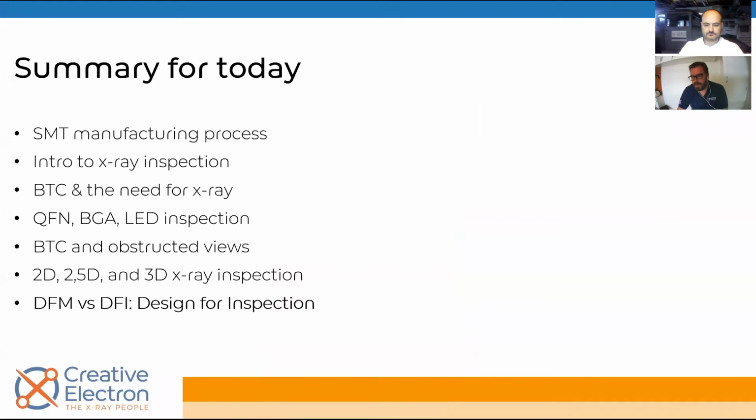So here's a quick summary we're going to go over today. If you've joined another one of these webinars, you're probably familiar with the SMT manufacturing process, where defects are introduced. A quick intro on X-ray inspection, BTC and the need for X-ray, QFN, BGA, LED inspection. All of those are different types of BTCs. BTCs and obstructed views. The difference between 2D, 2.5D, and 3D X-ray inspection, and DFM and DFI, which is design for manufacturing and design for inspection, and the difference between those two.